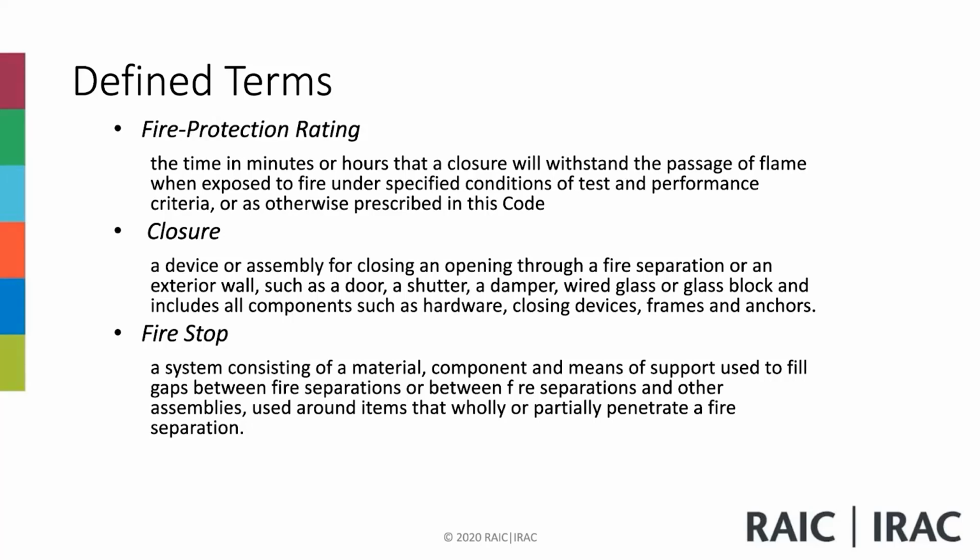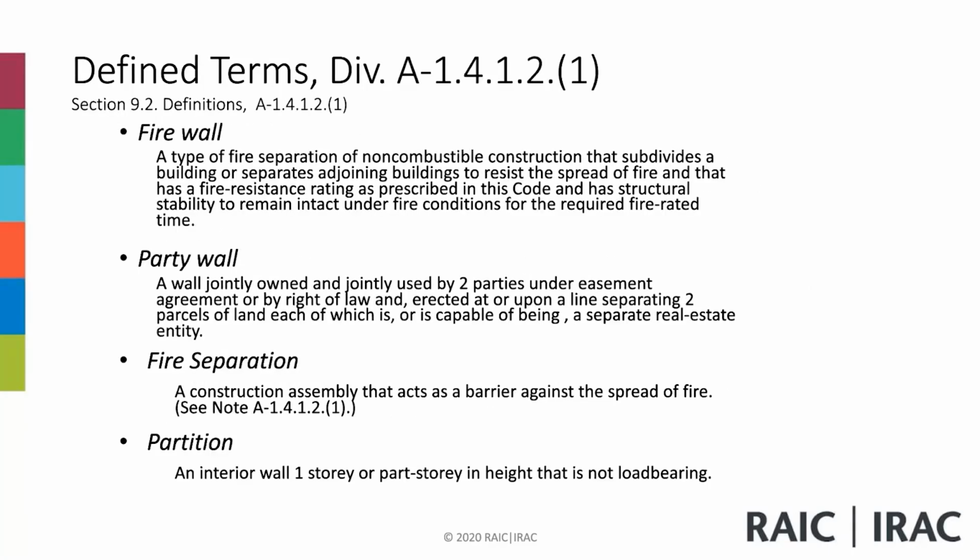Fire stops, we know that fire stops are components or assemblies between a fire separation and other assemblies, or between two fire separations. They can be joints or materials that fill up joints between fire separations or through fire separations, for perimeter or for fire penetrations, fire stop penetration systems.